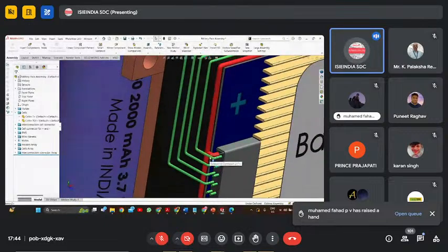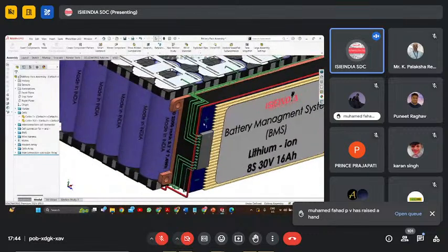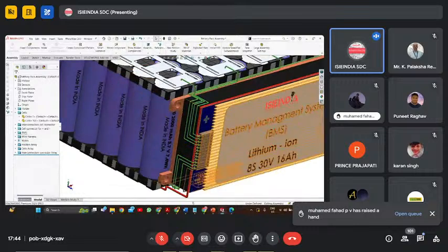First, the SolidWorks Electrical part is also there, from where we can do it. But here also, with the help of a 3D sketch, we can make a projector line from where we can take the wires and connections. After that we can use a sweep command, and we can convert this line into a wire. So if I go for it, I will show you once.